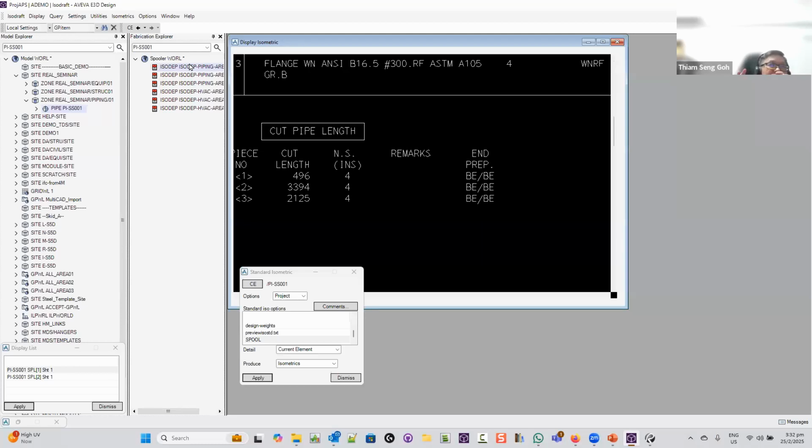Now we are touching on another topic. Somebody asked me, can you show us how to edit the item attribute, if we want to change the branch size, outlet type, dimension, or socket, etc.? Of course it's possible, but you have to change it in a logical manner. To change the branch size, if you have an existing 4-inch pipe and you want to make it 8-inch, you change the whole branch and it can automatically select the 8-inch components for you.